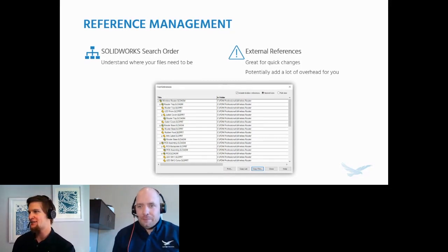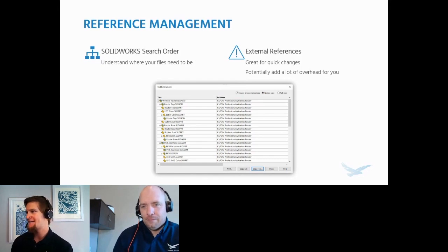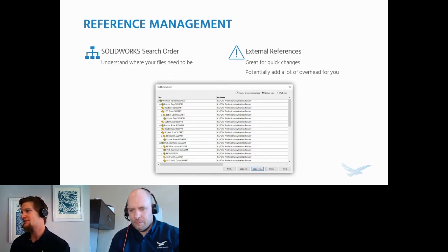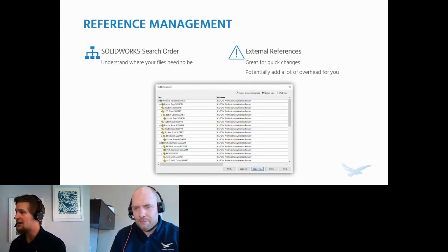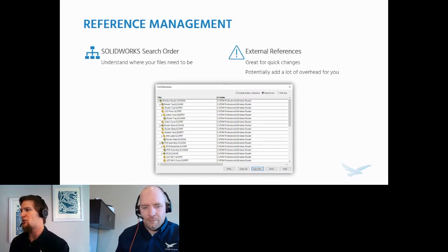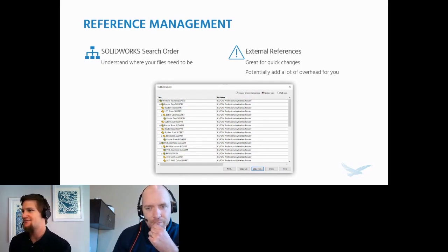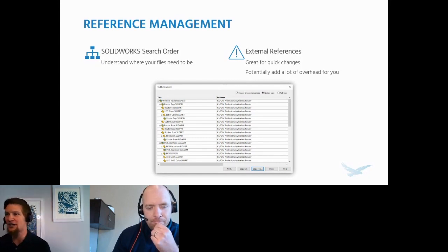Let's see what we got here. Looking at the results here. We got some votes for the right answer. It looks like the majority, pretty close. It was a tie between last path used by the system and the last absolute path when the parent document was saved. What is the right answer? It's going to be the last absolute path where the document was saved.